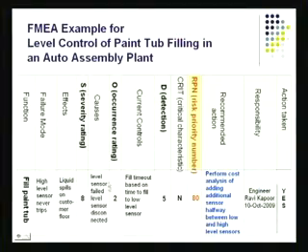If it is critical, action has to be there now. Then, of course, you multiply 8, which is severity, times the likelihood, which is like 2, which is 16, multiplied by detection capability, which is 5. You end up with a number that is 80.